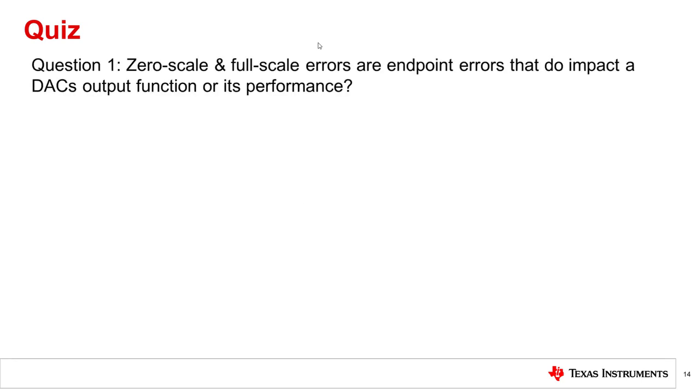Now let's complete a short quiz to check what we've learned today. Question 1. Zero-scale and full-scale errors are endpoint errors that do impact a DAC's output function or its performance. The answer is B, or false. Zero-scale and full-scale errors are outside the output function itself.